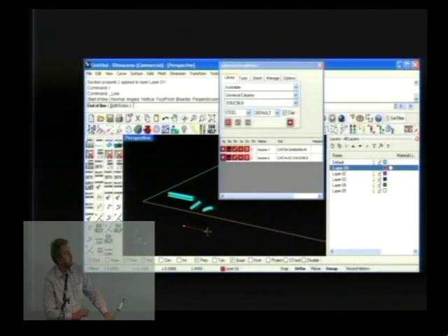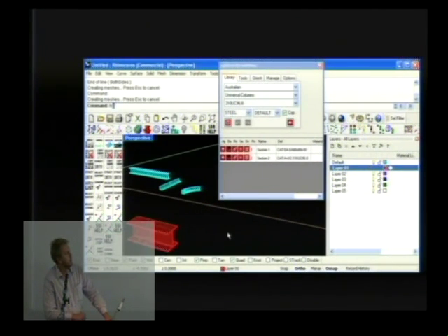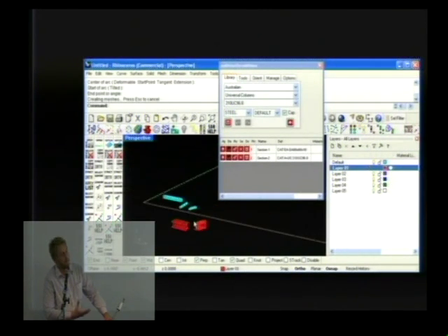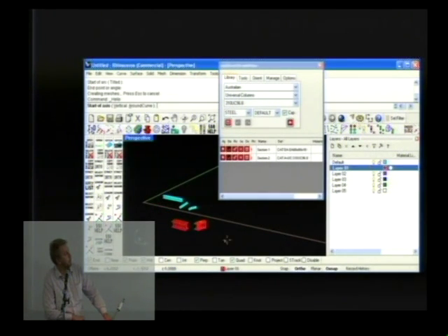That can either be applied to curves in Rhino, or you can apply it to layers. So if you've applied it to layer 1 and then you draw a curve on layer 1, then it will draw that profile on that section. Again, this is showing it done manually, but by the same concept, you have a component in Grasshopper when you have the plugin installed, and you just feed the input in, whether it be a curve or points and the property number, etc.